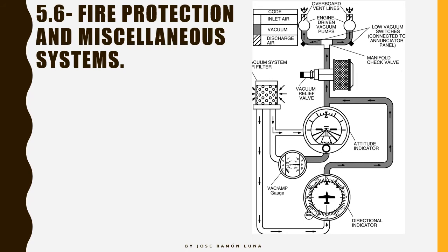One of them is by using electricity. Some of the big airplanes carry these big, expensive instruments that are connected to an electrical source that is going to allow us to have better precision and basically a system that is more reliable. However, in this small aircraft, we prefer to move these gyros via vacuum, because if we lose the engine, we don't want to lose all the instruments.